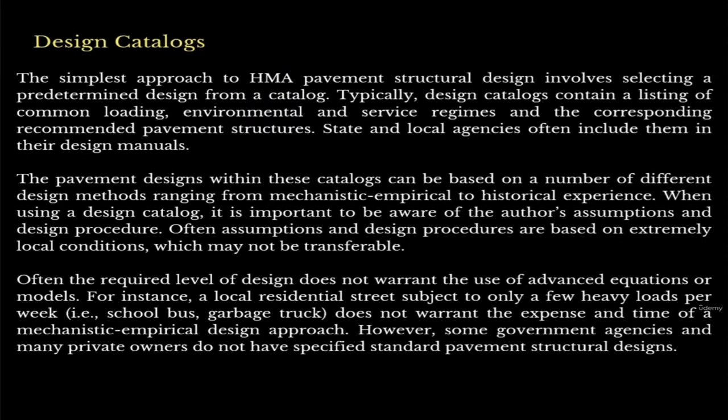So we'll start with talking about design catalogs because they're the most common and they're the ones that are most in practice. The simplest approach to hot mix asphalt pavement structural design involves selecting a predetermined design from a catalog. Typically, the design catalogs contain a list of common loading, environment, and service regimes, and a corresponding recommended pavement structure from the state or local agencies, often included in their design manual.